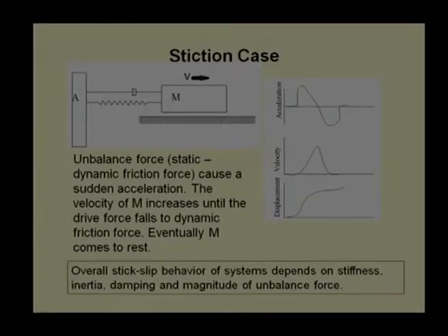And as we have attached one viscous damper and stiffness, we can say the overall stick-slip behavior of the system depends on the system stiffness, the system damping, and the difference between the force required for sliding and the force required for continuous sliding. So, overall performance will depend on this.